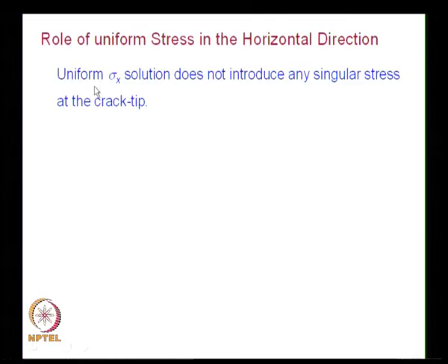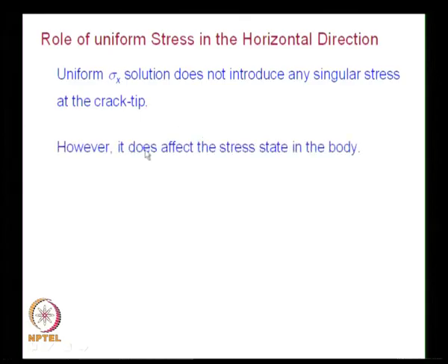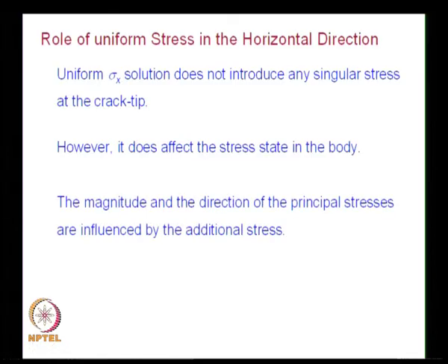If you look at the addition of the sigma naught x stress term, you have to notice this does not introduce any singular stress at the crack tip. This is observation number 1. What is observation number 2? It definitely affects the stress state in the body. If you are going to calculate the magnitude and the direction of the principal stresses, they are influenced by the additional stress, you cannot ignore it.